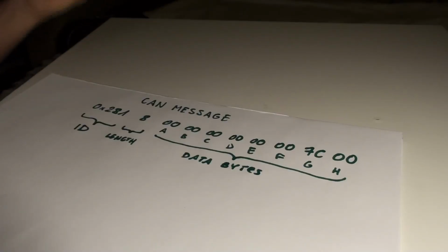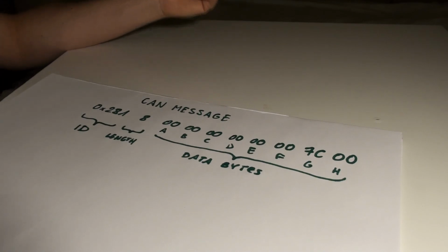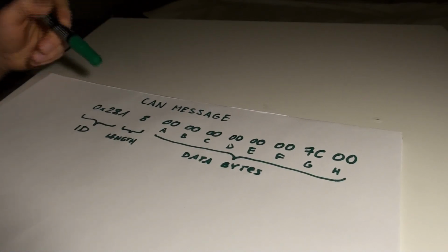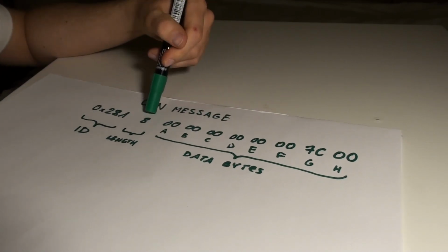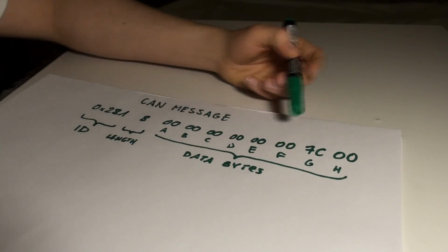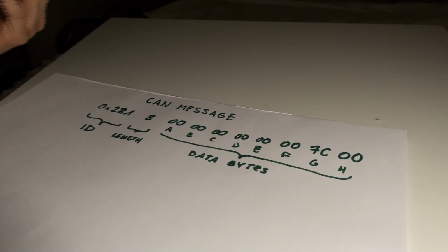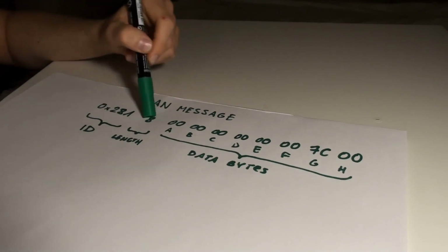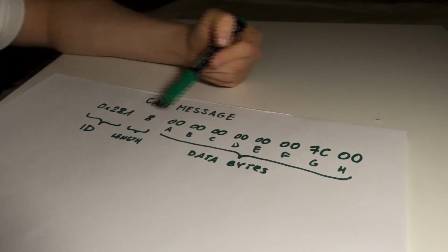On a level that is relevant to this project, I know that there is much more to a CAN message than just this, but a typical CAN message consists of those three main parts. The first part is the ID, which is written in hex. Then there is how many data bytes there are, so it's 8 in this case. And then you have the data bytes, which are also in hexadecimal. So the ID tells you what type of data or what parameter, like vehicle speed, a particular frame transfers. Then you have this length that I talked about, and then you have the actual value somewhere here in this data byte field.